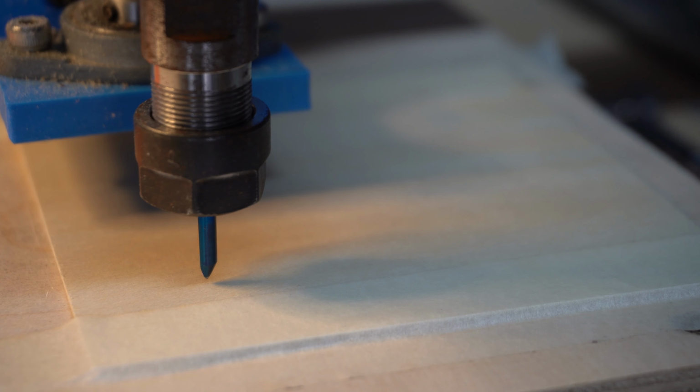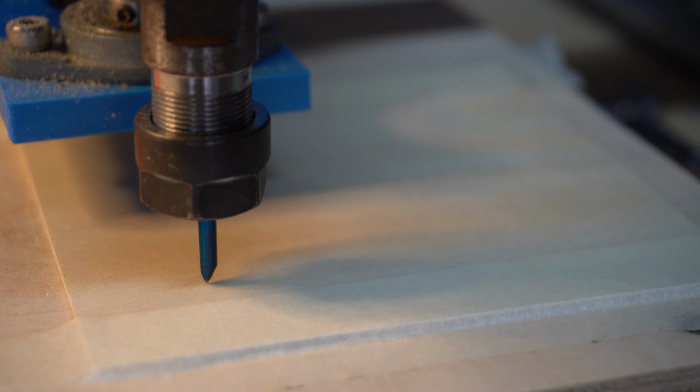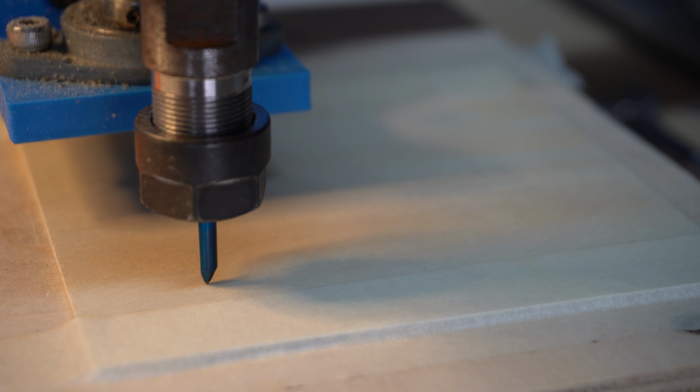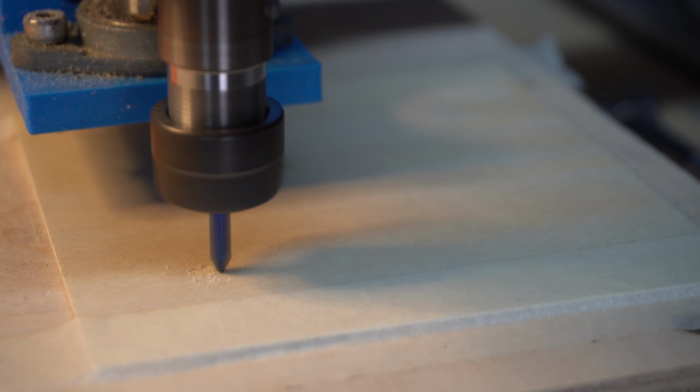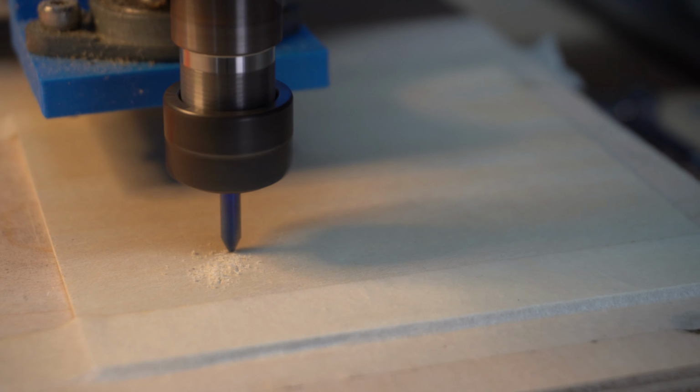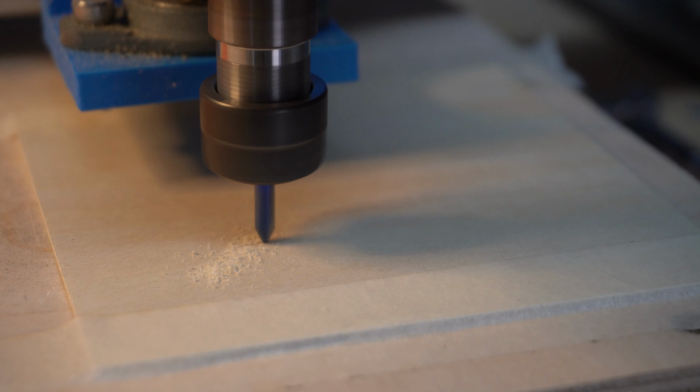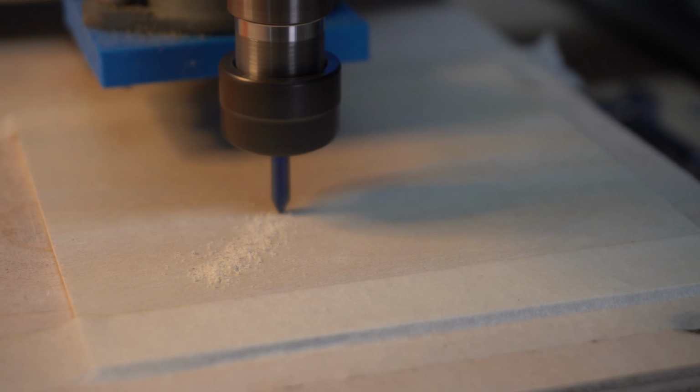In terms of the Y position, I try and position the cutter just slightly pressing into the material. Because this is such light material, it is very forgiving in the depth that you engrave to. Also, by pushing in a little bit more, I kind of ensured that even if there's a portion of the piece that's a little bit higher than the others, hopefully the cutter will still make engagement with it and still engrave the pattern.